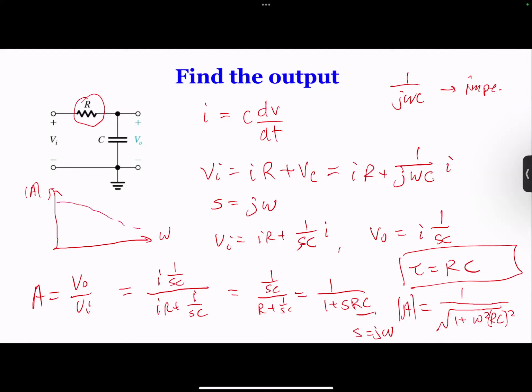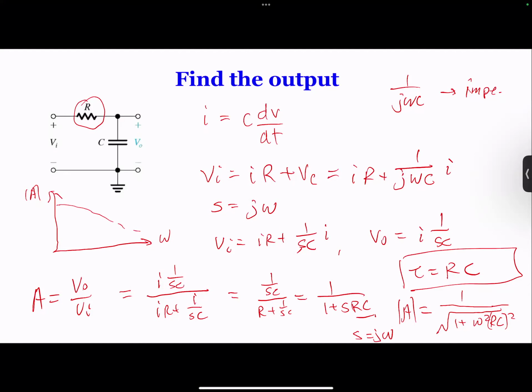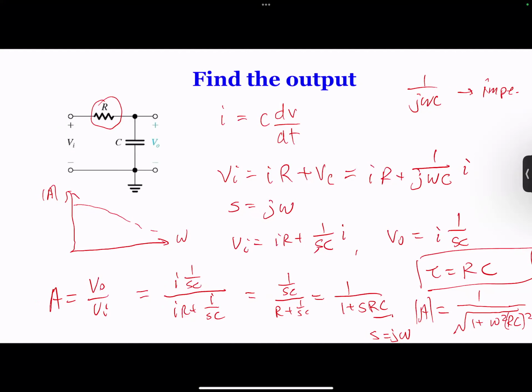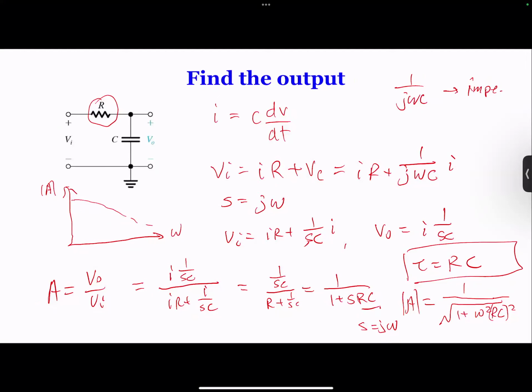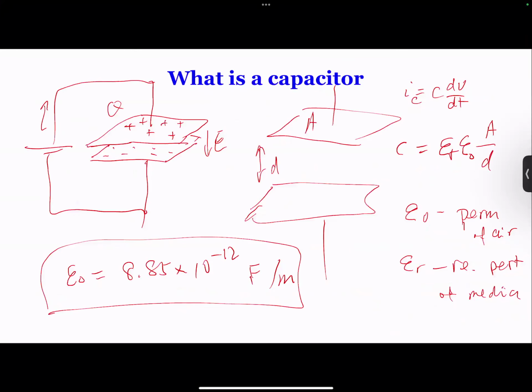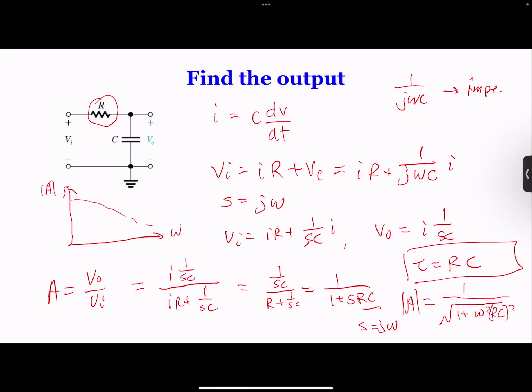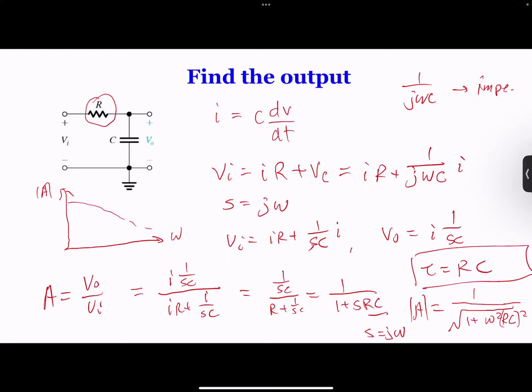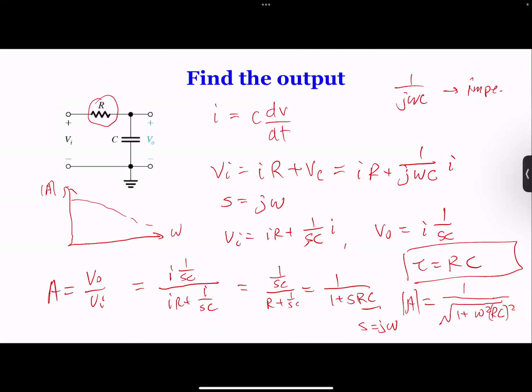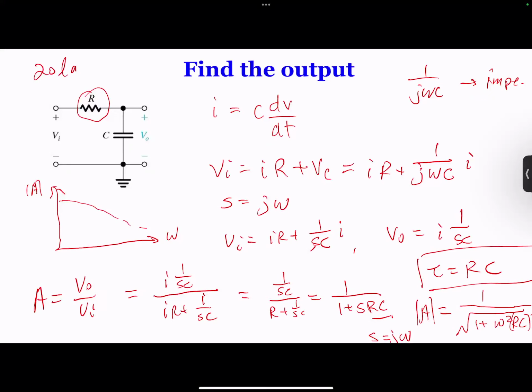Okay. But in circuits, what we found is that sometimes we actually want to compare different circuits, and I want to increase the gain. So far we have talked a lot about the voltage gain being 10, 100, or 8,000, whatever that gain number is. But in electronics, they actually use a different number. They call it dB. So for dB, they use this Bode plot. They simply use 20 times log.